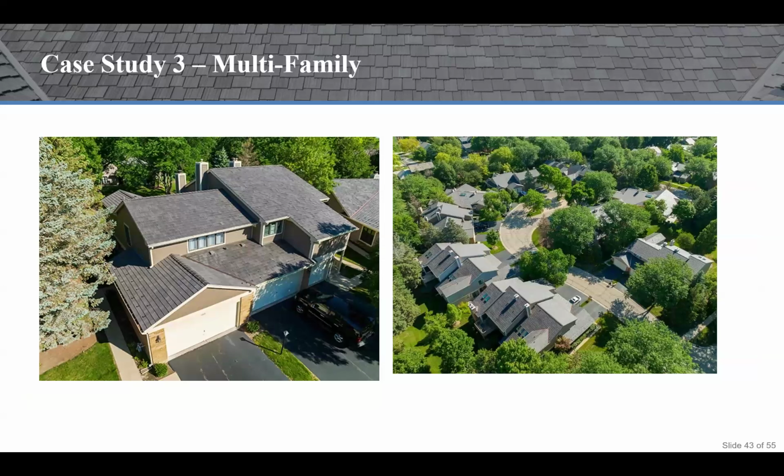We have our multi-family case study. This is in Libertyville, Illinois. This is a townhome community. The story here is that there are 325 townhomes in this community that needed natural cedar replacement. The original shakes were only 16 years old. The roofs needed to be replaced because of the premature breakdown of the natural cedar, primarily due to the roof being installed incorrectly. It was installed on a solid deck rather than cedar breathers.